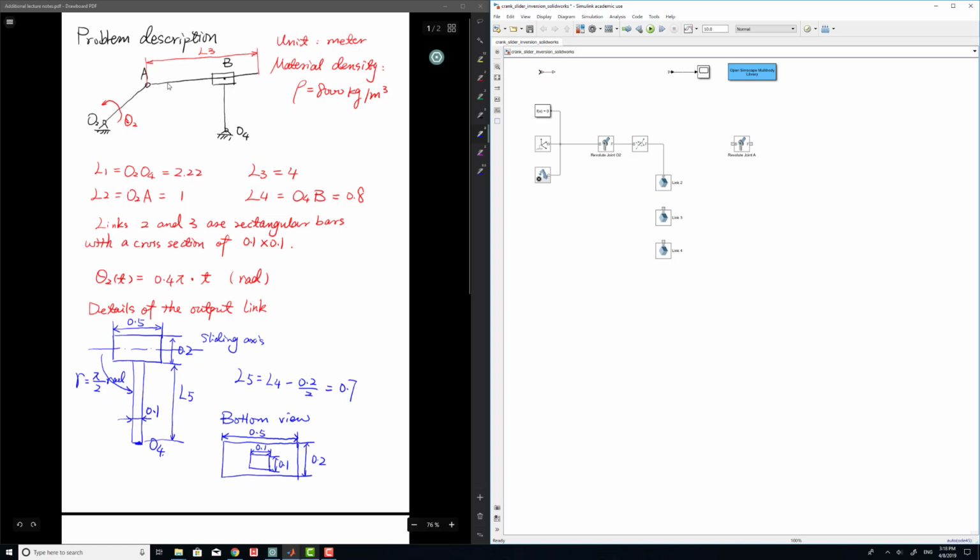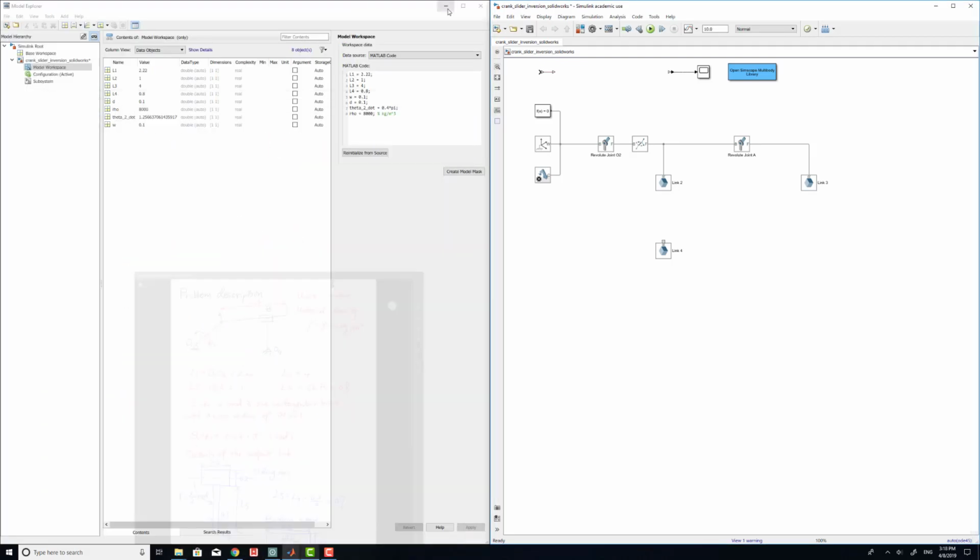And then on the other side, your joint A is connected to this L3. So we know that we need some rigid transform, but we don't know exactly how to transform it. So no worries. We first connect everything and then click run to see how things are connected in this way, and then we can make changes.